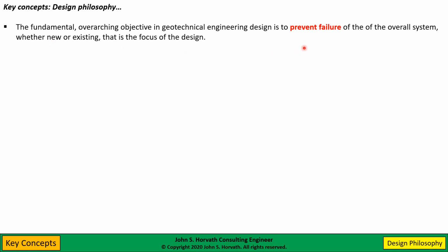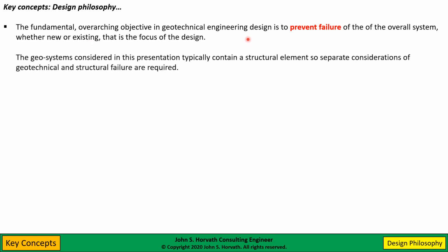And I want to emphasize that one of the real benefits of using geofoam for pressure reduction is that it is extremely useful not only for new construction but existing structures. And that's a real benefit of geofoam. The geosystems I'm going to consider today typically contain a structural element. So we have to separately consider geotechnical and structural failures as necessary.